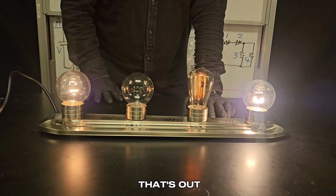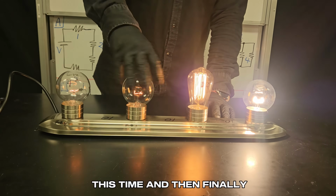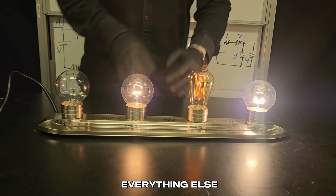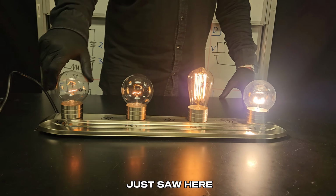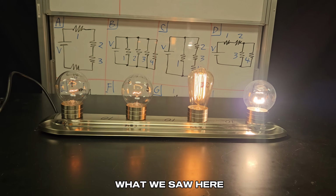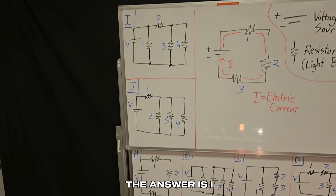it looks like 3 is the only bulb that's out. Everything else stayed on this time. And then finally, unscrewing bulb 4, again, everything else stays on. 4 is the only one that's out. So based on what we just saw here, what is the correct answer? Which schematic diagram matches what we saw here? And it turns out the answer is I.